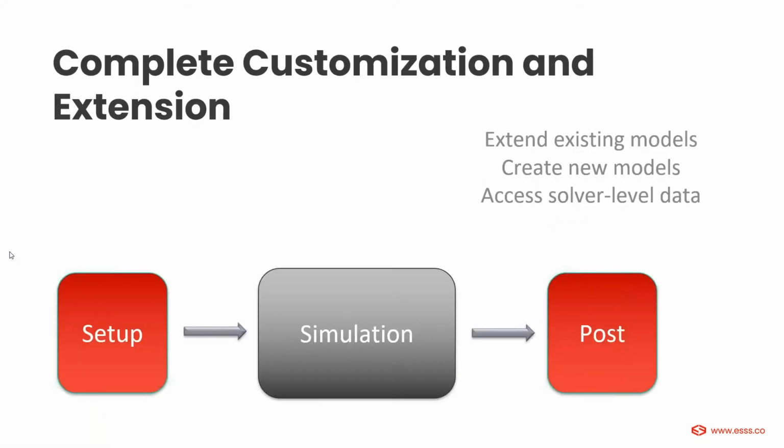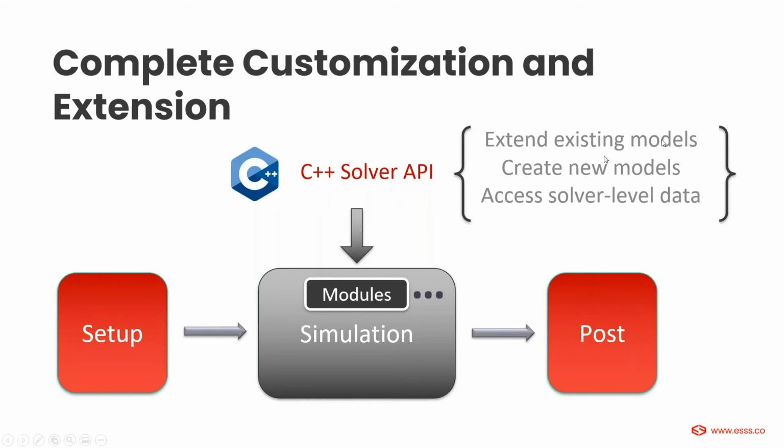Okay, and now the greatest part here is that Rocky is now completely customizable. We have released, with the latest official version, the Solver API, which is basically a way of extending existing models, or you can also create new models. And the greatest part is that you can access solver-level data. You don't need to access only the data on an output level, but you can interact directly with the Rocky solver by creating what we call modules.